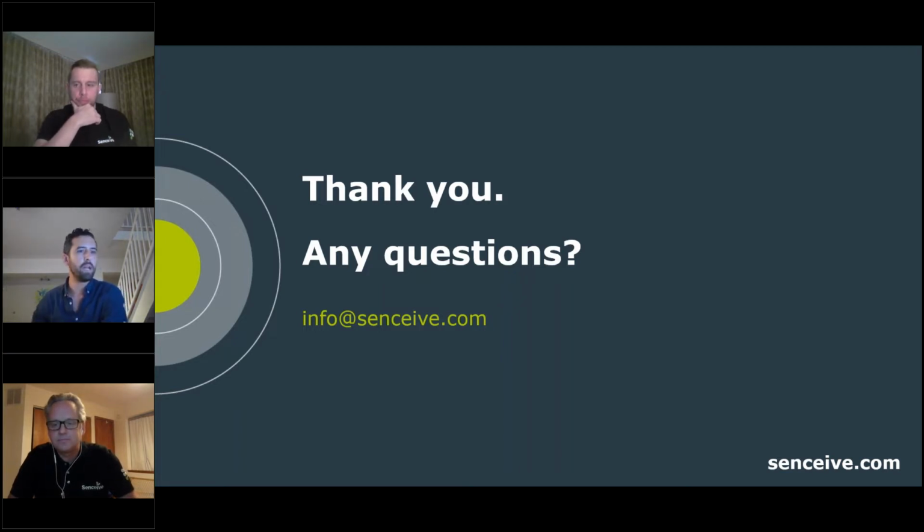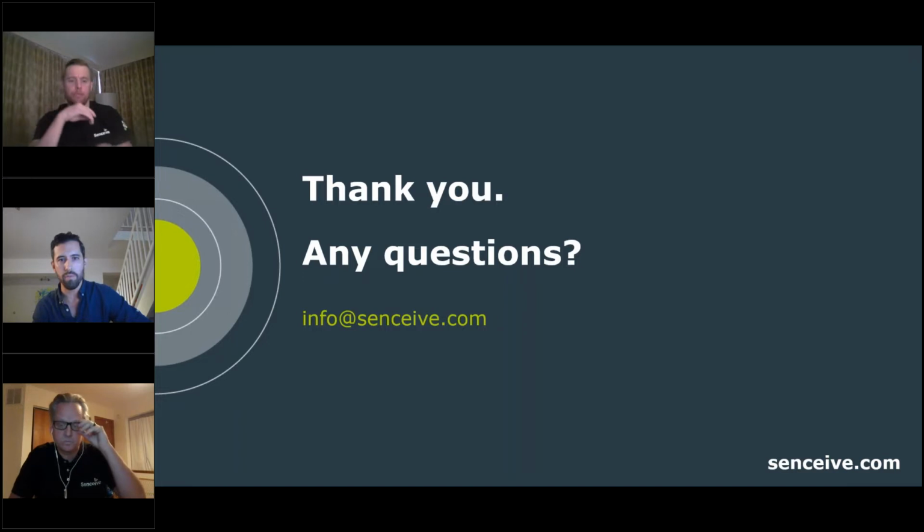Got one more I'll jump in on here before we're getting close. What sort of accuracy are you getting on the laser distance monitoring, and what sort of distances can be monitored? On our ODS sensor, the laser module that we use is a class 2 laser. So it's very similar to a total station. What we accomplish with that up to 150 meters, which is our range, is going to be plus or minus 0.15 millimeter. So it's a highly precise and repeatable measurement that we're accomplishing with the ODS.